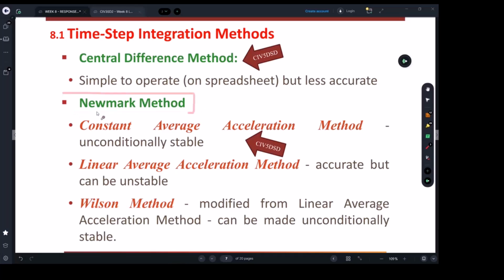The Newmark method, by its own, has three kinds of branch methods. And what we're going to be using is the first one here. The rest give you more accuracy and different conditions to work with. It just gives engineers the opportunity to use different methods, depending on the condition they have. The condition I'm talking about is comparing the available time step of integration with the actual time it takes one pulse within a time history to happen. So first, we have to make sure these kinds of excitations are covered.